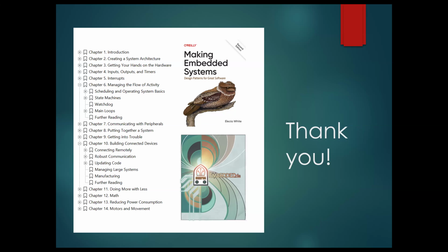Okay, let's see. What else do we have? What are the merits of building embedded software from scratch versus using boilerplate HAL libraries provided by silicon vendor tools? Well, if you want to learn things down to the ground, building embedded software from scratch is very interesting and useful. But if you want to ship software, if you want to ship hardware, if you want to actually get things done, then use the HAL libraries.